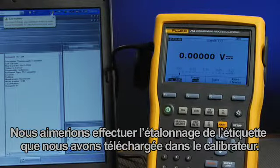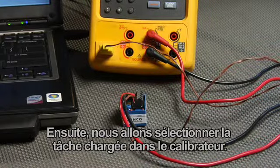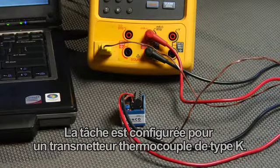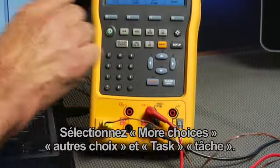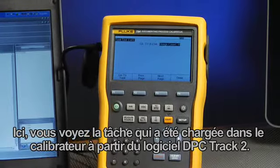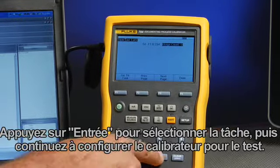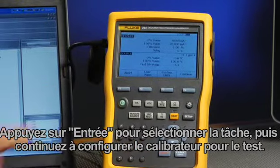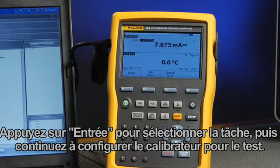Now we would perform the calibration of the tag that we've downloaded into the calibrator. Next, we're going to select the task loaded into the calibrator. The task is configured for a Type K thermocouple transmitter. Select More Choices and Task. Here you see the task that was loaded into the calibrator from the DPC Track 2 software. Press Enter to select the task, and then Continue to configure the calibrator for the test.